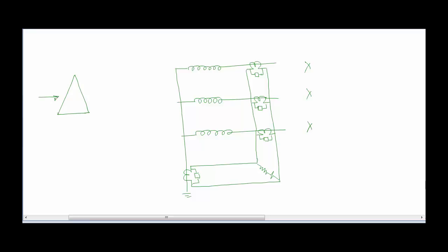So there is a supply of voltage on the delta side of the transformer, then we say that it is in charged condition, and once we close the circuit breaker and put load on it, it is going to draw current from the system. But in this situation it is going to draw only the magnetizing current. But if a fault takes place, then it's obvious that the fault current will be drawn by the transformer from the system. So in this particular situation, let us assume that there is a fault at this point.